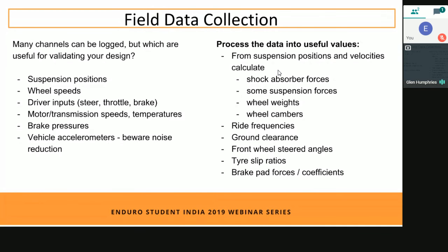And once we start driving and you're monitoring and logging your suspension positions, then you can see, okay, we're using most of our ground clearance, but not all of it. So we could actually lower the vehicle, either now or in future. We could lower the vehicle and have better stability, better cornering without running into collisions.